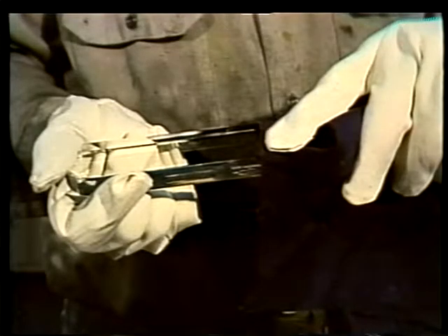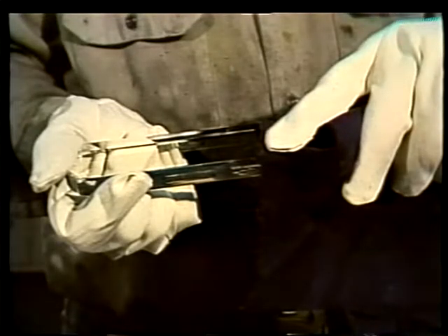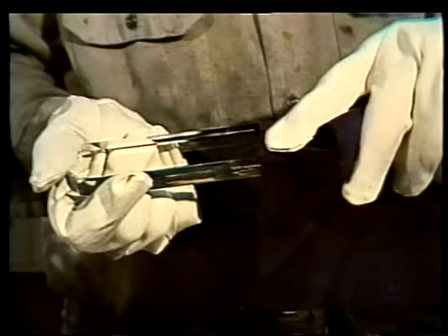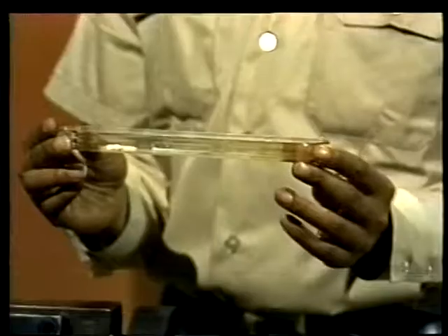It may be necessary to replace the glass with new glass. Some manufacturers recommend replacing the glass whenever it is removed from the gauge. If you decide to reuse the old glass, it must be thoroughly cleaned with a soft, damp cloth. Don't use steel wool, a scraping tool, or an abrasive detergent to clean the glass. Inspect the glass for scratches, clarity, and erosion.